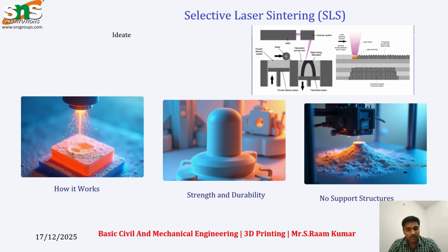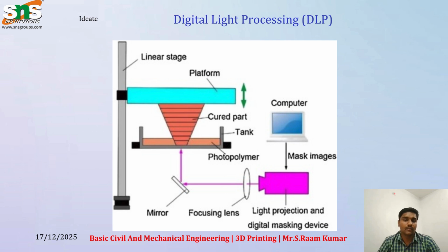But producing the metal powder takes a huge cost. So, in order to develop selective laser sintering as a mass production, commercially available printer, we need a new technology for producing the raw material, which is the main drawback of SLS. But to develop complicated structures beyond our creativity, selective laser sintering plays a huge role.